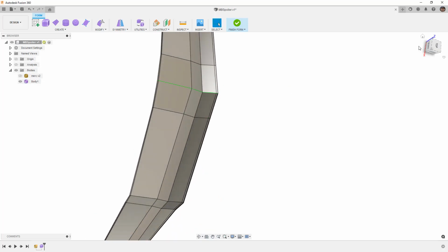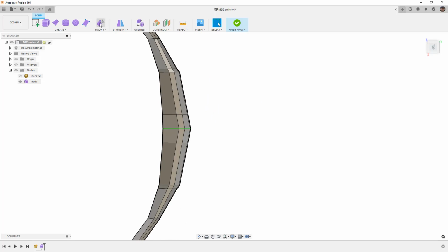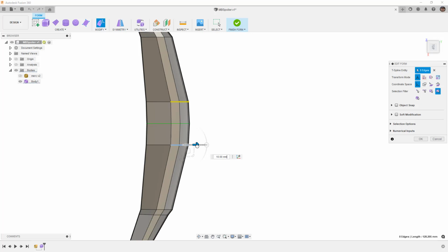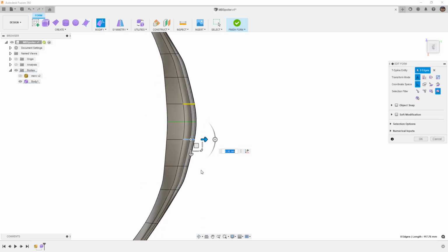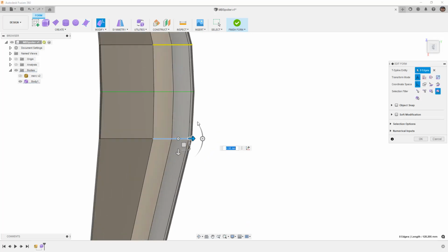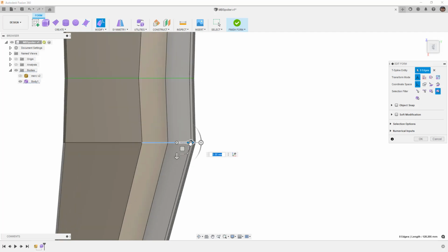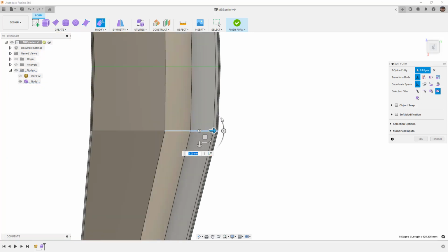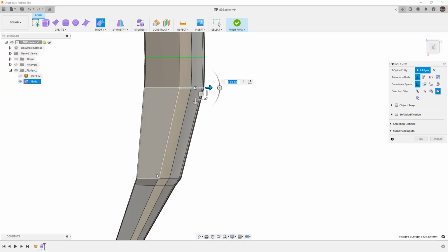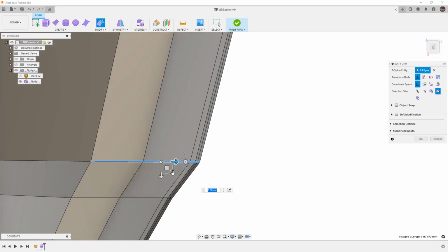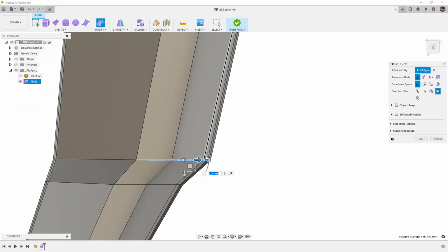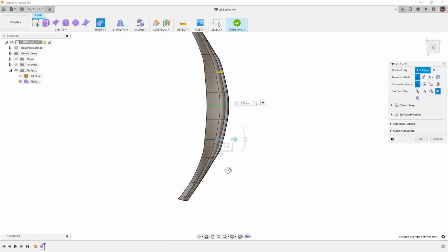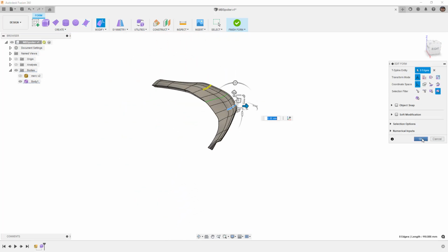Looks okay. And now if I want to make any tweaks or adjustments to the shape, I just need to be very careful with what I'm selecting. So box select, I'm going to pull all those out, take a look at it in smooth display, maybe pull them out a little bit more so it's closer to flat. And again, if these divisions are too much, you can zoom in or you can manually input them. And I'm going to take these, I'm going to zoom way in and pull them out just a little bit. And notice that I'm not bringing the whole thing. I'm leaving the edge at the car where it is. And again, that's going to help me tweak the shape a little bit.